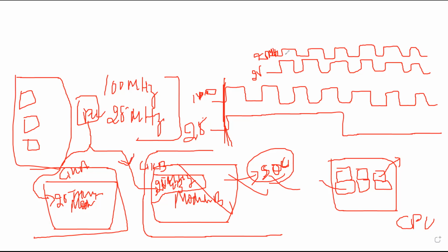The clock can have some jitter values. So from just seeing the architecture, we can't say whether it's a synchronous or asynchronous clock. We can guess that it should be synchronous, but you can only rely on it when you see the waveforms. Now you have got what the basic synchronous clock is.